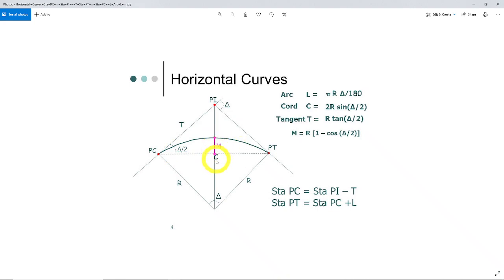And we have other things like this chord bearing here. If it went from PC to PT, point of tangency, this would be the chord bearing, which also has a chord length. This is the tangent length. So if this curve and/or arc was not here, and these lines theoretically shot out and intersected, that would be the point of intersection. This is a simple curve, our arc, aka both. This is the tangent distance, and this is the delta, but in this case it's going to be 90. This M, I'm not sure what that is, the mid-ordinate distance or something. We won't talk about that.